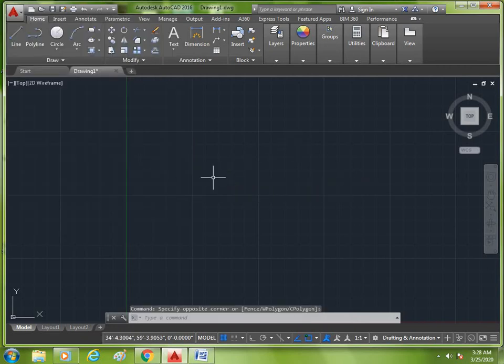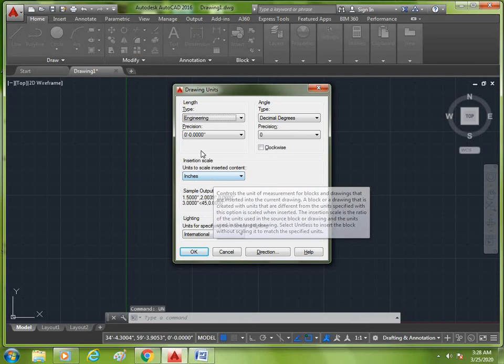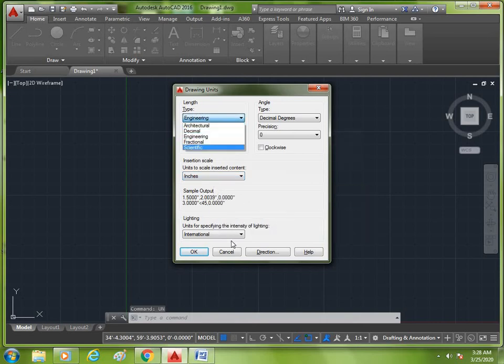But in AutoCAD, mostly we work with shortcut keys. So type UN and press enter, and the space bar is used as enter. You can use the conventional enter button as well, but for more convenience, we can use the space bar. So after typing UN and pressing enter on your keyboard, you can press the space bar, and then you can directly select your units and drawing limits.